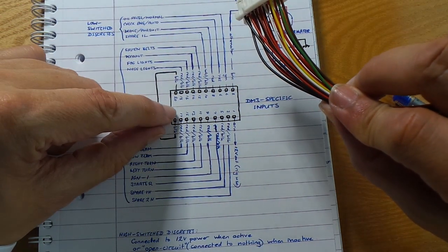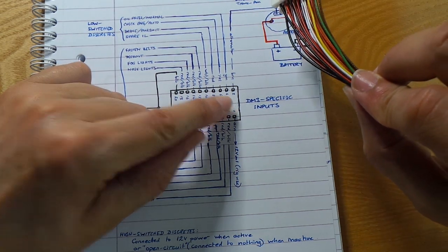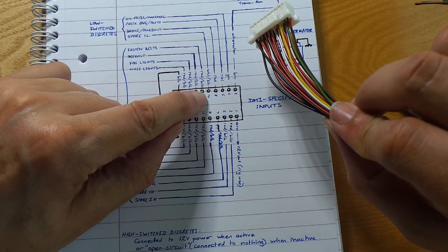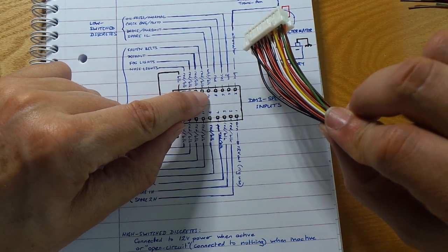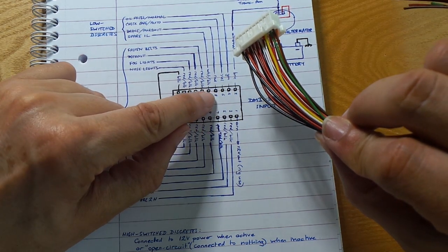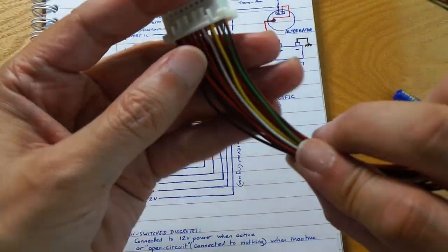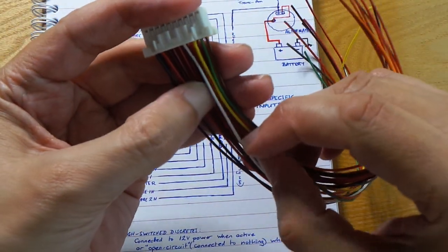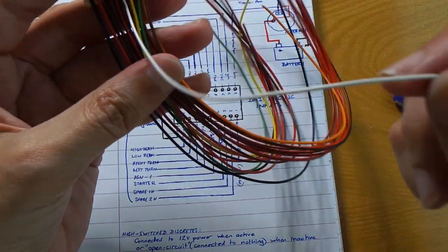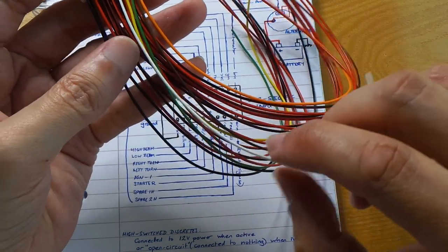So let's look at the other inputs which you'll need if you're using the module in its fully functional mode. First of all, we'll leave this brown input until last, but all of the other ones, this pin number 10 here is a spare ground switched discrete input. So that's like the normal auto and pursuit, it's a ground switched input, but it has no specific function in the default configuration. If anyone wants a customized version of the software with a ground switched input, we can provide that on that pin and write a custom version of the software to accommodate that.